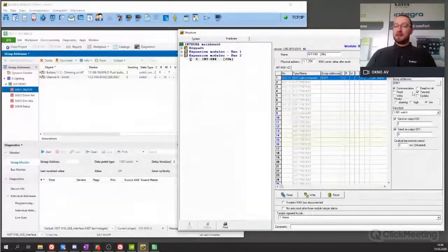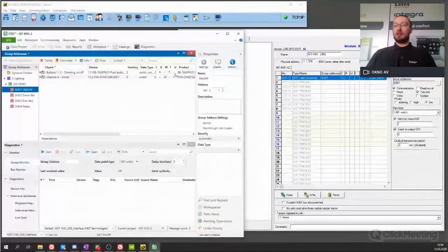A little bit more about the flags. These are the KNX flags, and as you see in here, we have CRWTU, the same here, the same part is here. And this information is set properly as the default for output, zones and macros. I don't want to go too much into depth of the information in here, but in general, these flags you can leave as they are. Maybe if you want some additional functionality, then you can change them depending on how you want to control it from ETS or have the additional functionality. But in general, you can leave them as the default, it will be fine.